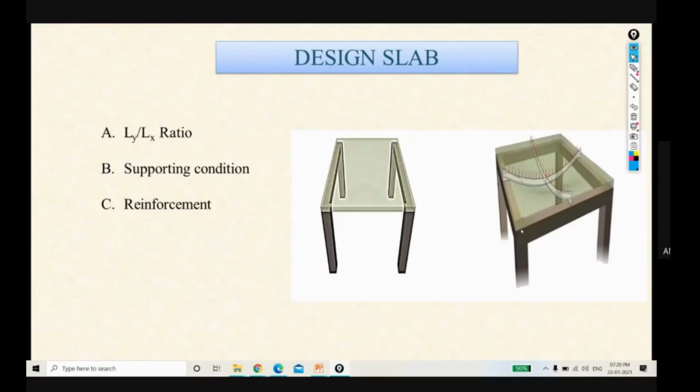and from the theoretical point of view, in a two-way slab our slab is supported on all sides. It is what theory accepts, but if we go to the field, I mean if you consider the field point of view, then in a one-way slab also your supports are on all four sides. So that is the difference between theory and practical.